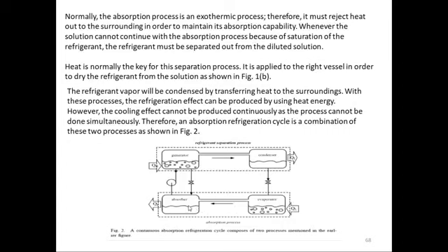So this is the absorber, okay, and this is the evaporator. The cooling effect is being produced here, and water vapor is being absorbed here in the solution, okay. So then what do we do? We send this solution using this pump into the generator. In the generator, we are supplying the heat. We are supplying outside heat into the generator. As a result of that, it will separate it,